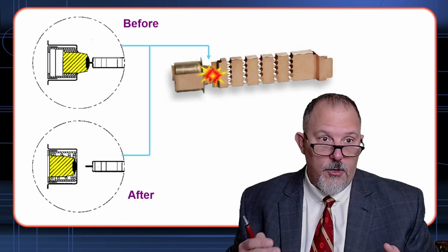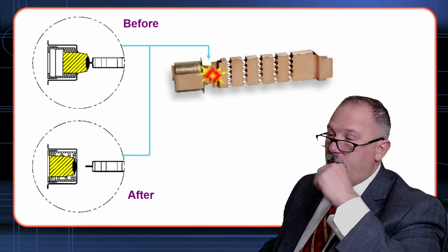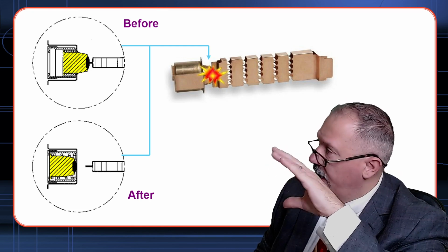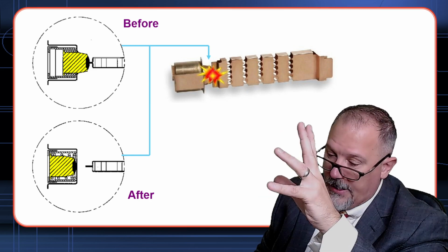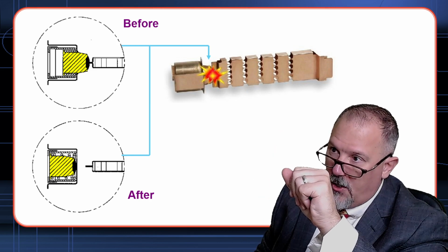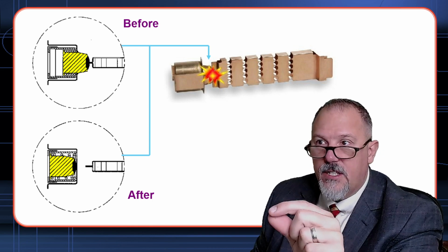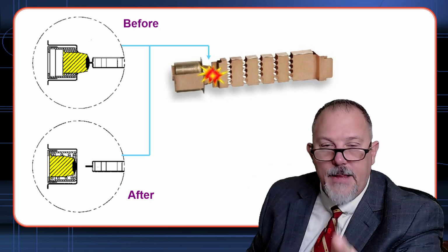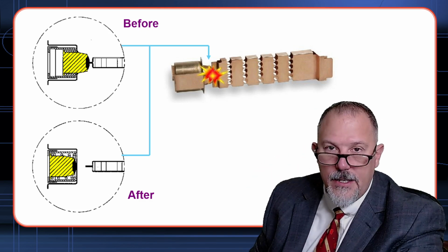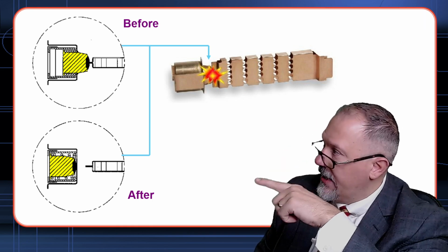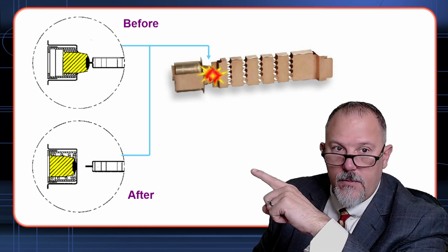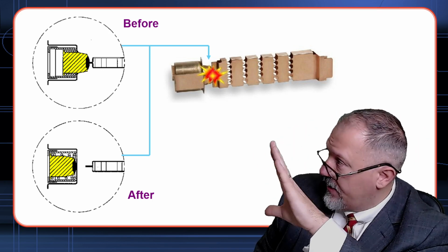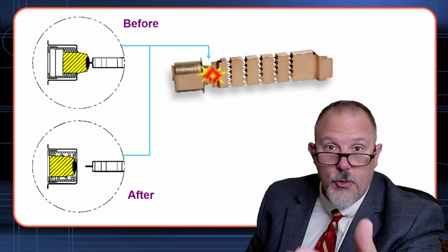So on the overload, what I'm showing here is a pinch point, or how would you call it, a tiny pin that has tension on it based upon a spring, and that pin, when heated, can be melted. Hence, what we're showing here is that the pin is together up top, and then it separates down the bottom when you heat it.